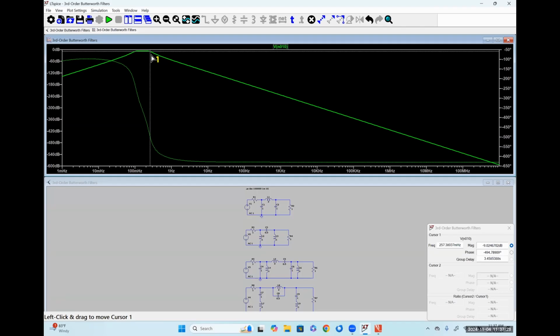Take the difference of those two things. So omega high, or F high minus F low. So it should be the exact same thing as omega naught, effectively. So our bandwidth and our resonant frequency are the same right now, okay? So we have 159-ish millihertz of bandwidth, and we have a center frequency of 159 millihertz as well. Or we have a bandwidth of 1 radian per second and a center frequency of 1 radian per second.